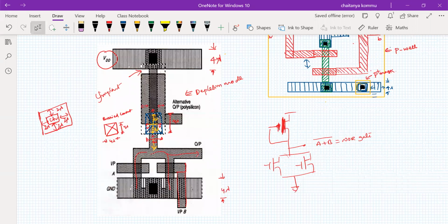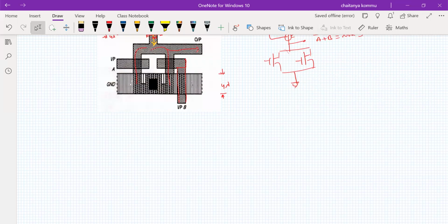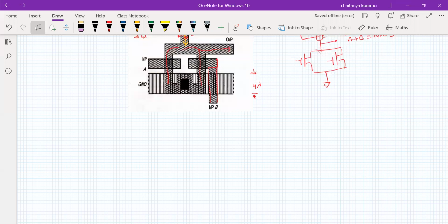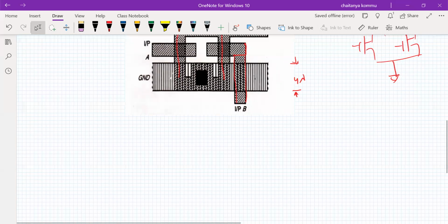Here a buried contact is required because the polysilicon and diffusion are connected together at that particular point. Therefore, we use the buried contact, with its dimensions according to the design rule. By looking at the layout diagram also, it is possible to say what kind of circuitry it is. Now let us quickly move on to another concept, called basic circuit concepts.